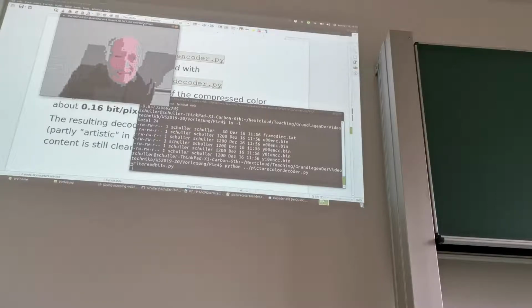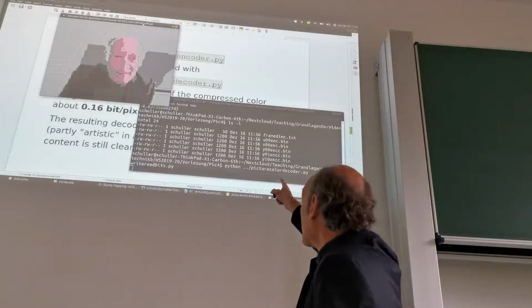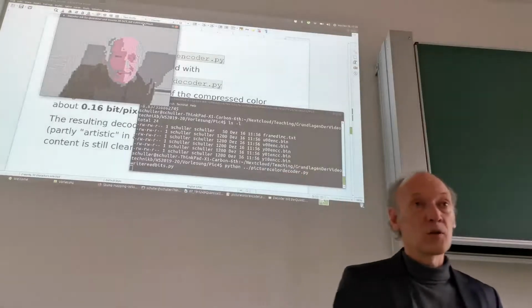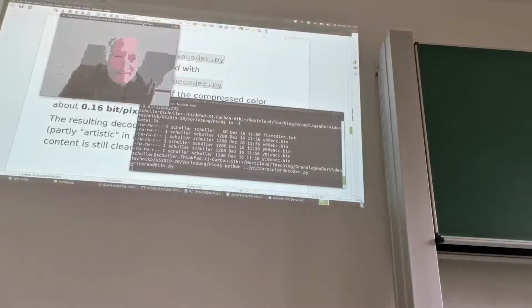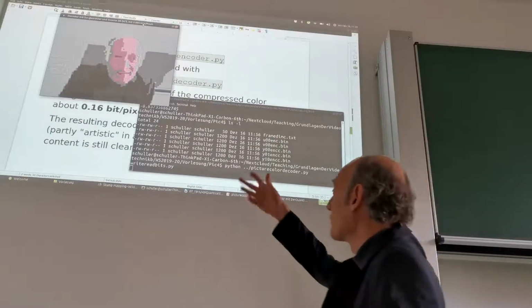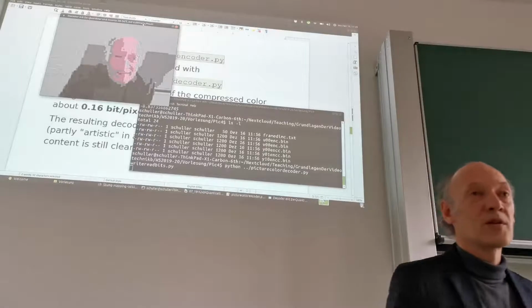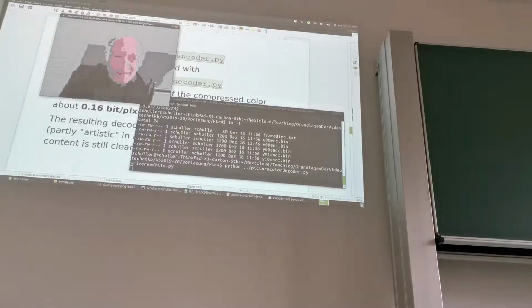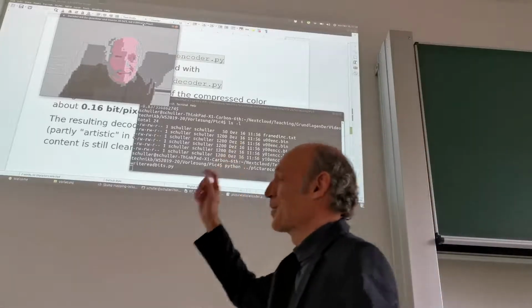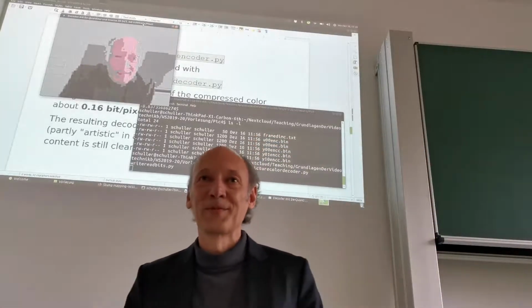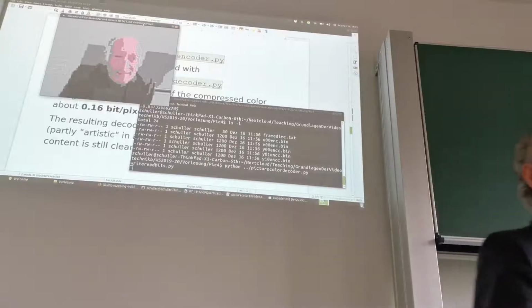And it's the quantization, right? So remember, here the color components, they determine the color, and I quantize also the color components with only 4 levels. So that means for each color component, I have 2 color components, each has 4 levels. That means we have altogether 4 times 4, 16 different colors possible. Right? And this is just one of the 16 possible colors. So that means the colors are not really true because it's too few. But at least it's color, right?